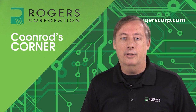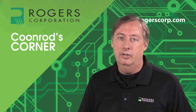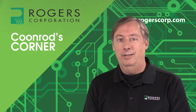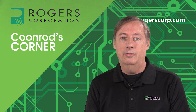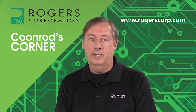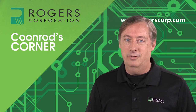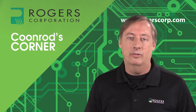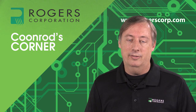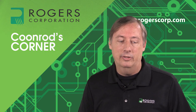To begin with, let me talk a little bit about test methods. IPC is one of the big industry standards, a group that makes standards for the industry. And IPC has probably, I think, 12 different test methods for determining dielectric constant. And then there's also ASTM test methods, there's OEM test methods, universities have them. I have a book that has 78 to maybe 80 different test methods for characterizing materials at microwave frequencies. So there are a lot of test methods, and there is no perfect test method. Each one of these test methods has its own set of pros and cons, limits and capabilities.